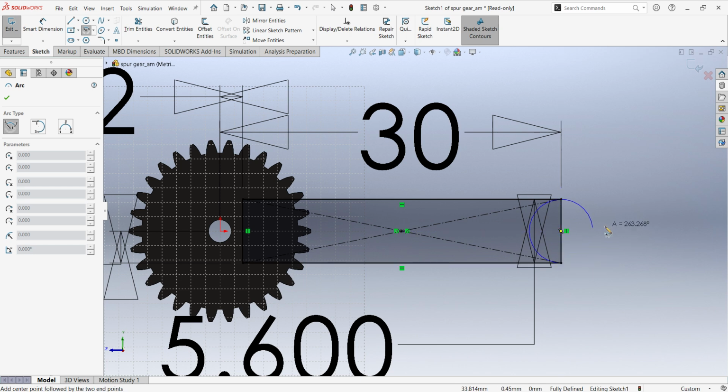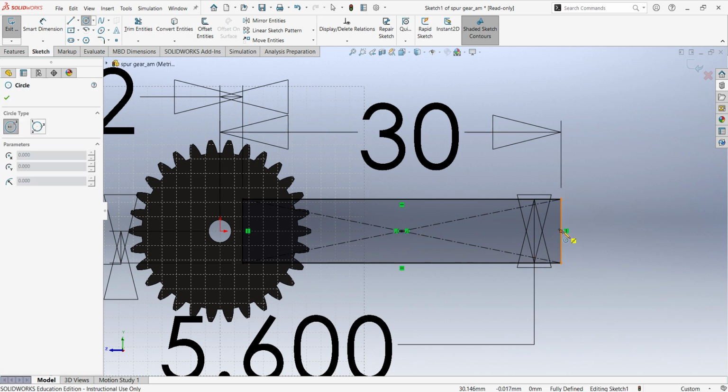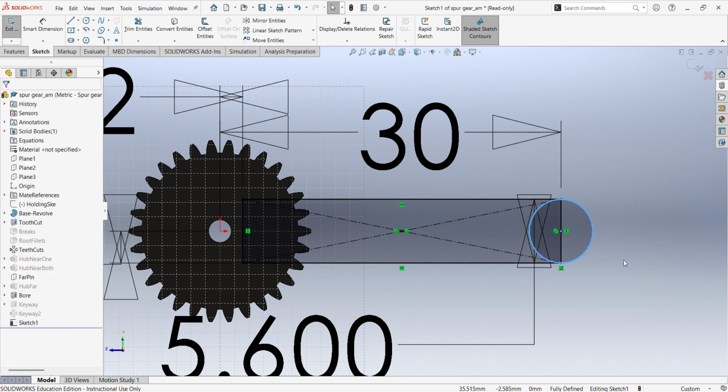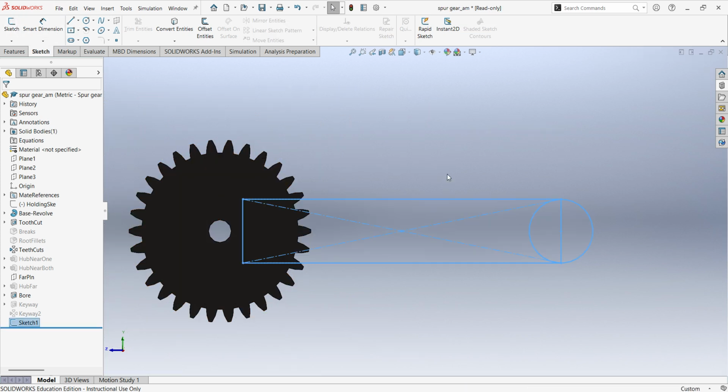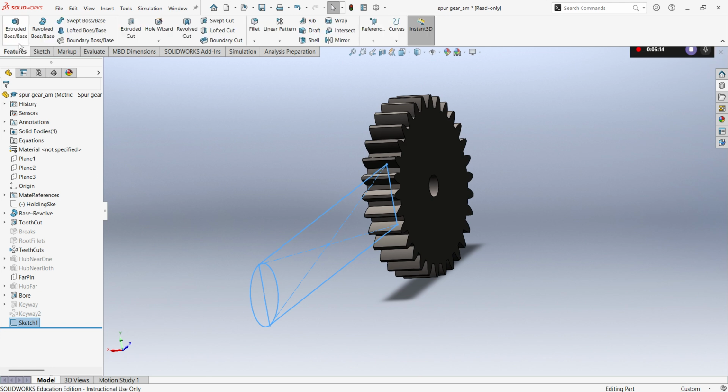If you hover over the line, you'll get a center point. Click that point, drag and click one edge and create an arc or a circle. It's easier for now. Create that circle, then you have it dimensioned everything.